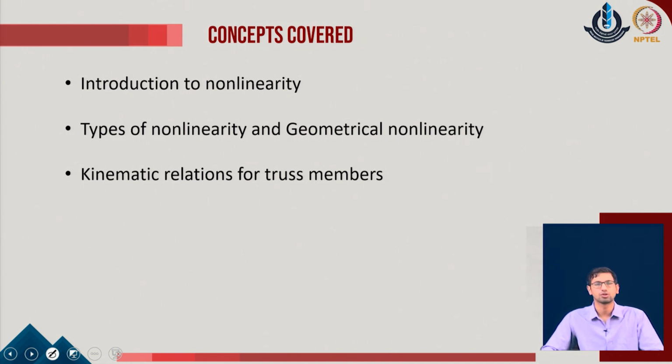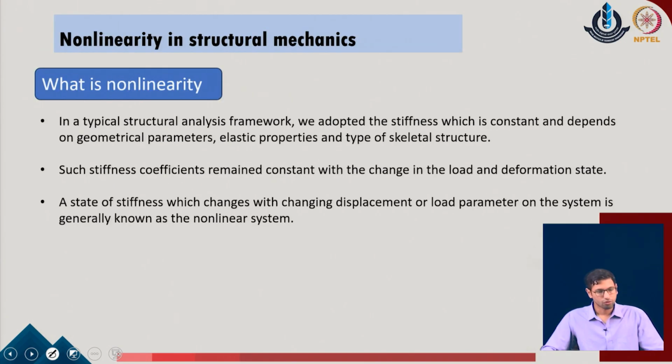Eventually we will also move to the material nonlinearity in the successive lectures, and then we would like to continue with similar relations for the kinematic relations of the truss members. Up to now, whatever we have been doing is valid within the linear framework of structural analysis, and there is a very standard concept of material nonlinearity or geometrical nonlinearity which many times we regularly hear. So, now we want to introduce these concepts in the context of structural mechanics problems.